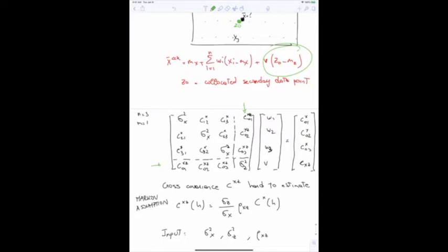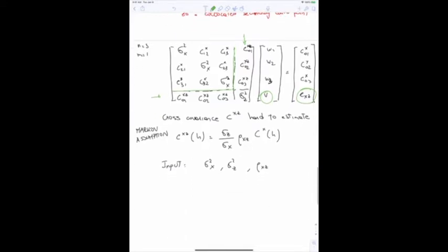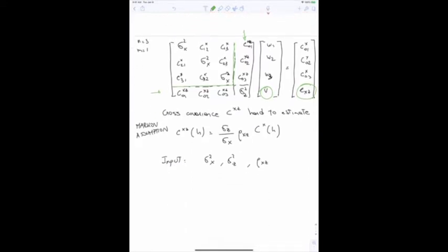And the first part is exactly the same. So this would be the same covariance matrix that we have used in the past for the simple Kriging. But now you have this additional weight, you have a cross correlation on this row and this column. But if you use the Markov assumption, you can compute the cross correlation by simply applying this equation here.